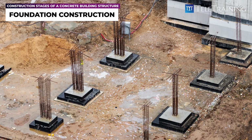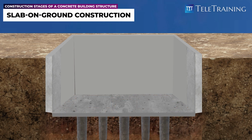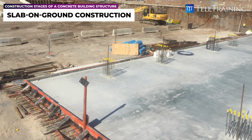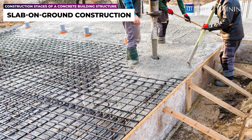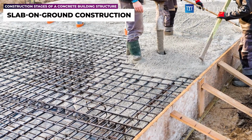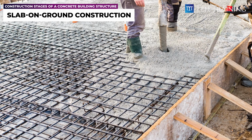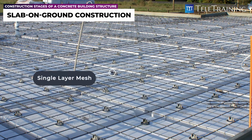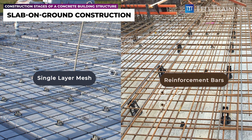Once the foundations have been constructed, the next step is to lay the building's first slab, which will be placed directly on the ground. Here's an example of what this might look like. Slab on ground is typically a reinforced concrete slab that has a uniform thickness throughout. It is often reinforced either with a single layer mesh or reinforcement bars at top and bottom layer, as you can see here.